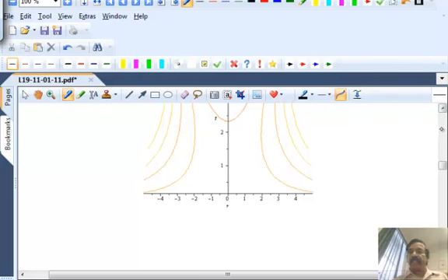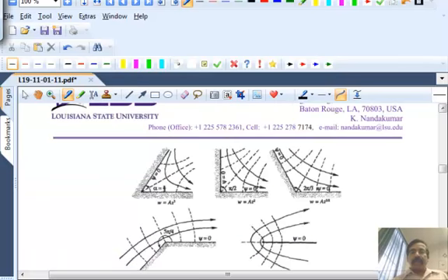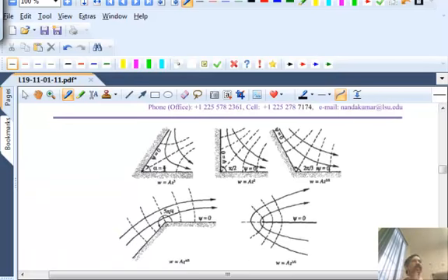And this, I think, is just the stream function and potential function. In the book by Kundu, I think Bird, Stewart and Lightfoot don't spend a lot of time on potential flows, just a few examples. But in Kundu, they have the sketch for various angles: alpha equals pi over 3, alpha equals pi over 2, 2 pi over 3, etc. So this entire class of flows past sectors, whether obtuse or acute, we can calculate from that single function that we have, z to the power n.